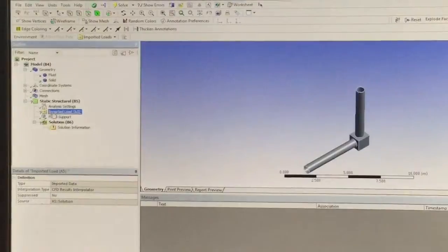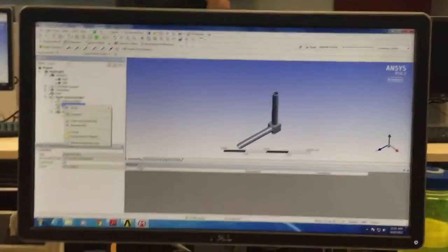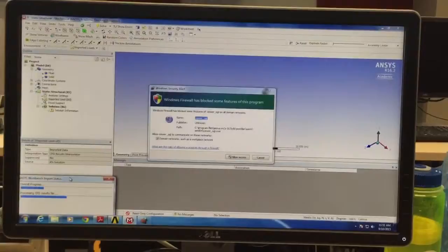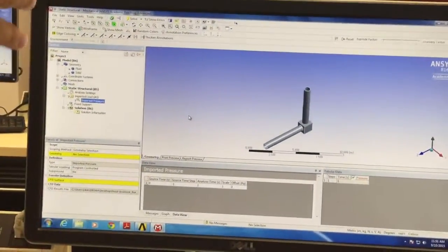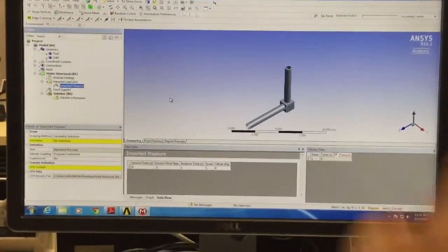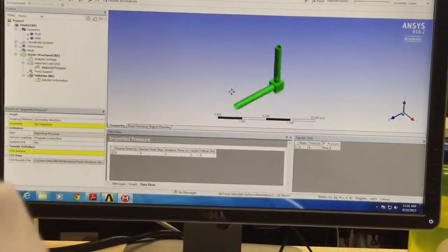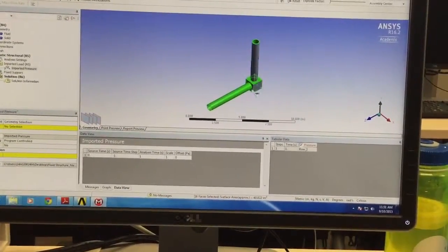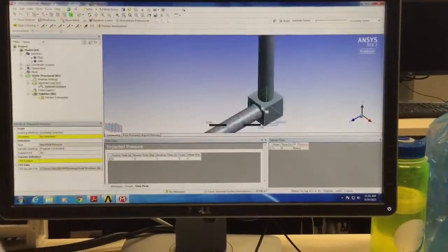Okay, then next we have to import the fluid pressures from the CFD sources. So right click, insert the fluid pressures. Firstly we have to select the internal surfaces that interact with your fluids, the ones that move. Then right click, select all. Because it's very hard to select internal surface, so just select everything then undo deselect the outside one. Correct. Those two also don't move, so we have to remove that.